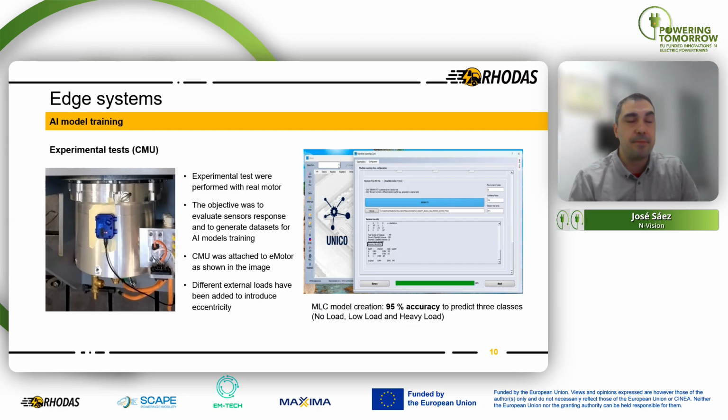On one side, the vibrations give us information about any potential eccentricity or excessive vibration on the motor, meaning that due to mechanical aging, the axis is gaining some eccentricity, or even that other external components of the motor are not properly tight, and these are inducing some movement on the motor.